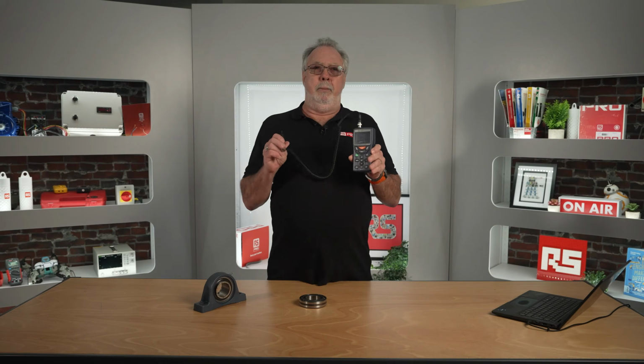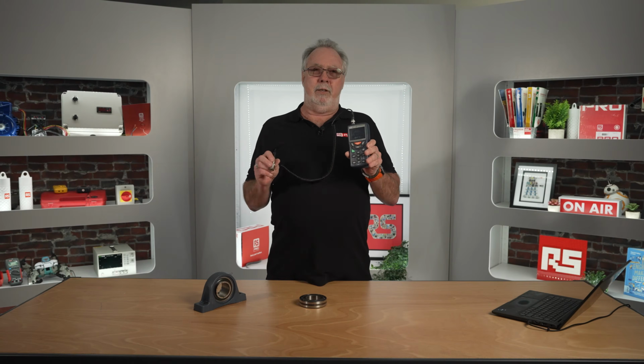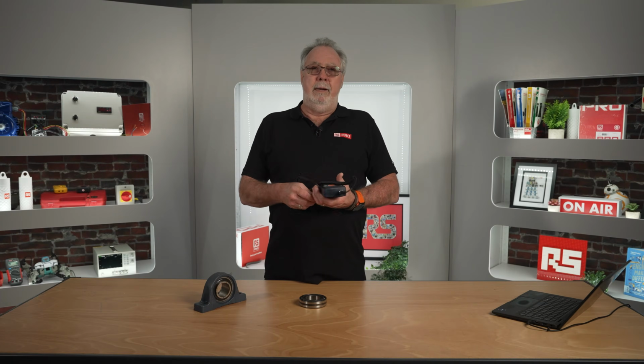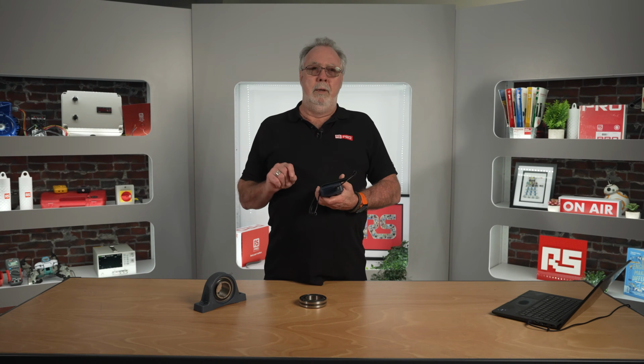This is a bearing analyzer, and it is used to detect vibrations within a bearing when a vibration has been felt or heard on a machine but not specifically where. The analyzer can be moved to various positions in the machine. Where you find the highest reading is where you're going to find your most probable cause of a problem.